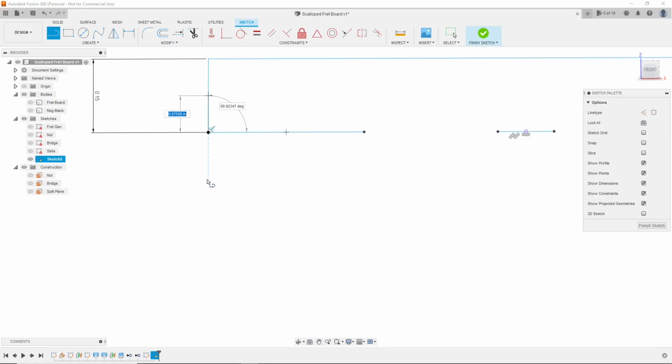And if I were to just click right here, it would draw the line on top, not on the bottom. I don't know why. But I'll show you how to get around it if it's doing it on your computer. This is the thickness of your scallops. So I'm going to do a 0.05. Instead of just hitting enter though, just wiggle it around a little bit first and then hit enter, and then the line will come to the bottom.